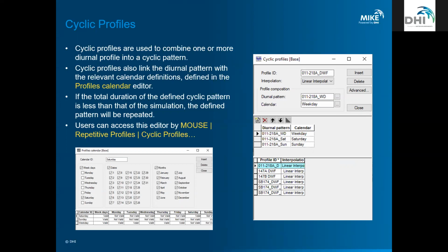And you may have the same pattern for every day, for every node in your network, or there might be different patterns based on water usage, depending on how the network is laid out and the population. So you can attach specific patterns to specific nodes, or you can apply it to all of them. This is the usage of the entire network.